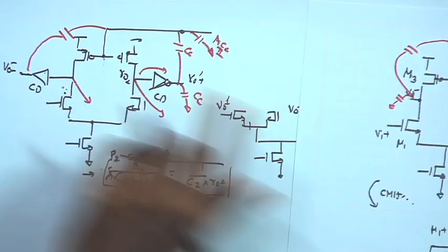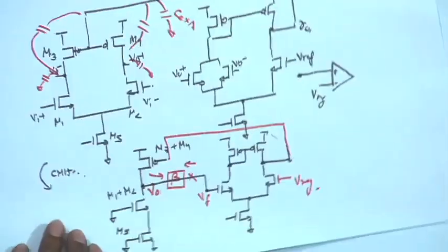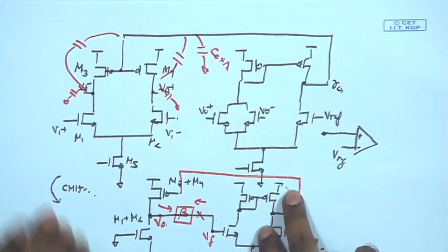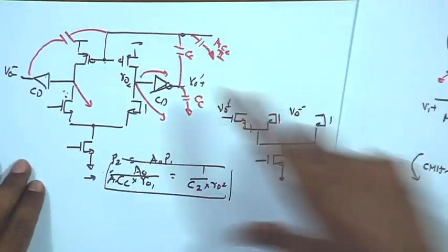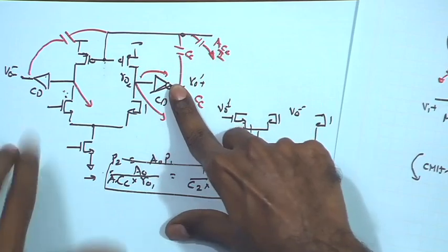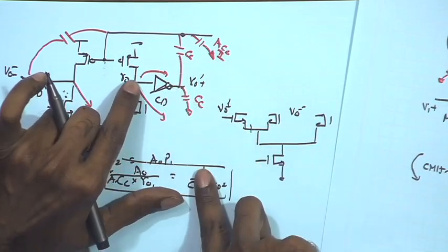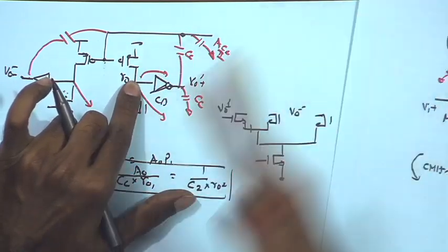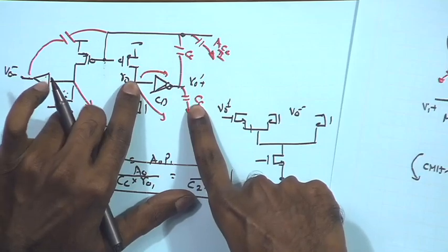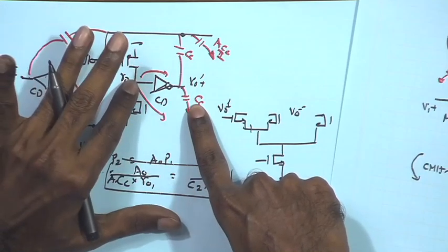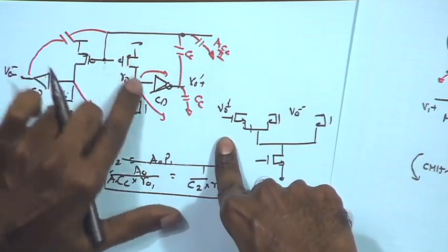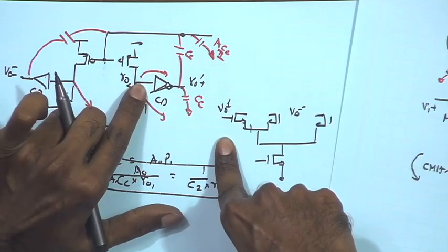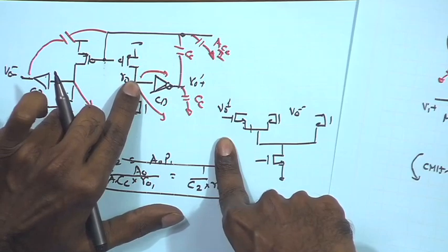So, for the higher frequency pole, if we look at our discussions over here, because of the large Cc value, the impedance at this node at higher frequency effectively reduces. It does not remain exactly RO, it goes down close to 1 upon Gm of the load transistors. Let us discuss that. We will look at that with respect to the differential operation also. It will become more clear.